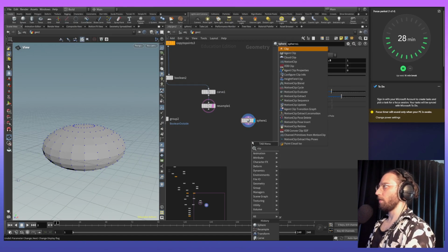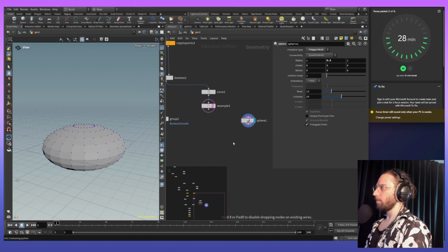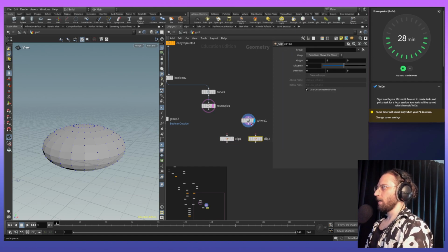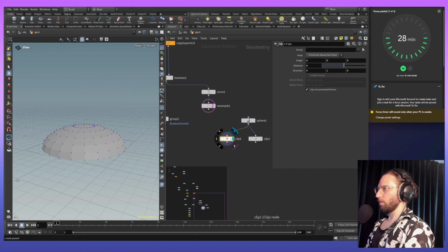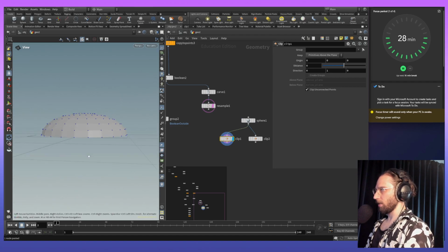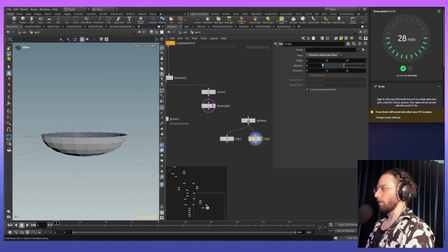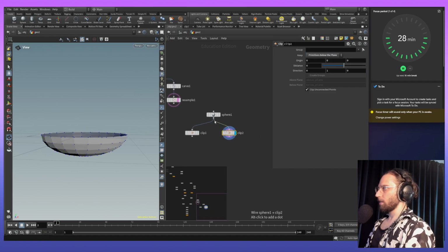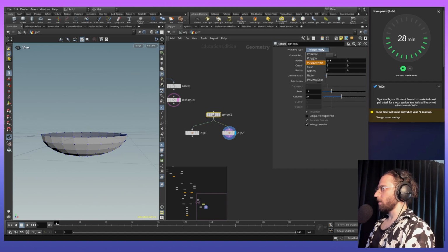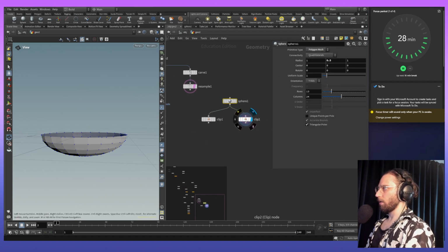So we will clip it from the bottom and from the top. We'll just see how that works in a second. We'll add one here, and we will add one here. And then if we view this, we should be able to see that, hey, this got clipped now from the top, and this should now be clipped from the bottom. So you just have to change that primitive here. And in the sphere, we just want to make sure that it's a polygon mesh. All right, things are working well for us.